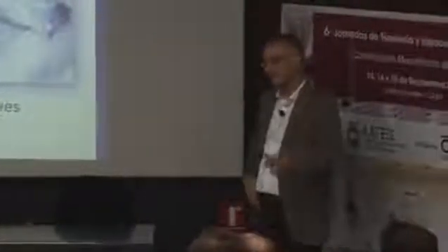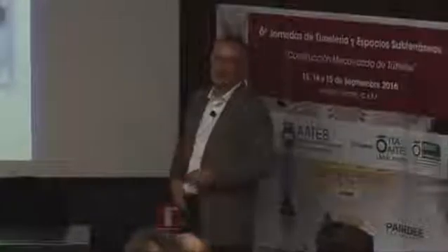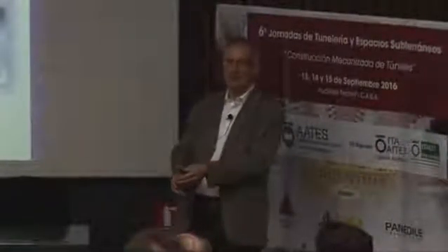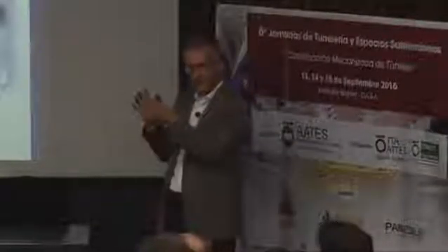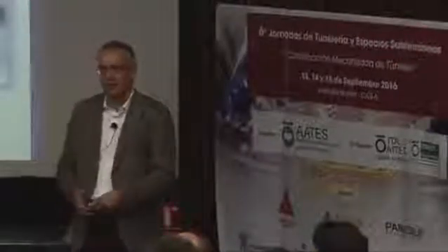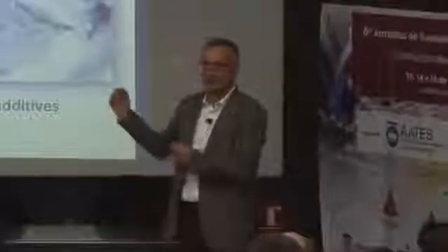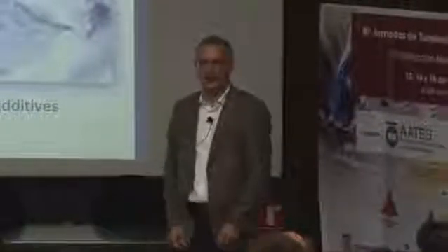EPB foam is one-off, so you inject it, you extract it, and it is lost. So you do not have a quality problem, as you have with a bentonite slurry, which you pump back in and circulate, and you have aging there. So with an EPB TBM it is more important to have the right foam generator sitting with the right parameters, inject it, and see how it comes out and how the TBM reacts. It is an easy flow, and once it is out of the tunnel, that piece of foam is history anyway.